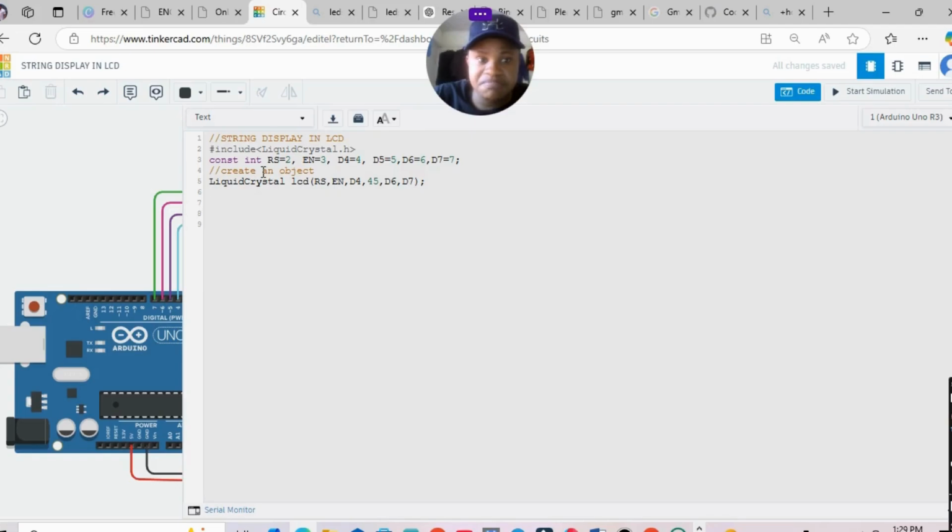From there, we are going now to set the serial monitor debugging rate, or data transmission rate, and also specify the LCD that you are using in terms of columns and number of rows. We are going to do that inside a function by the name void setup. Void, make sure they are in small letters. Not void loop, but void setup. Void setup. We have 2 brackets and 2 curly brackets. Then inside the 2 curly brackets is where we are going to write our code.